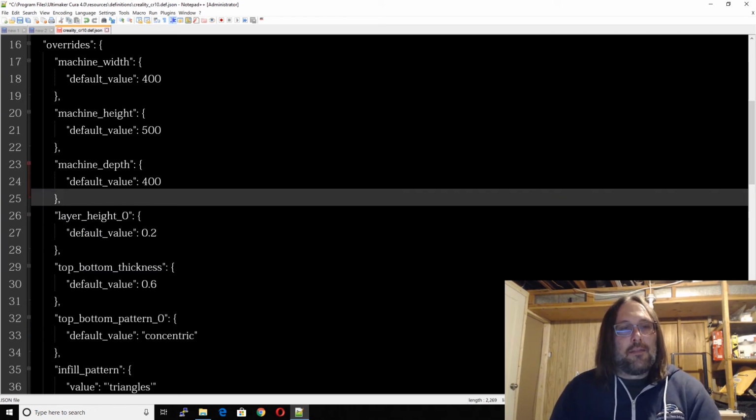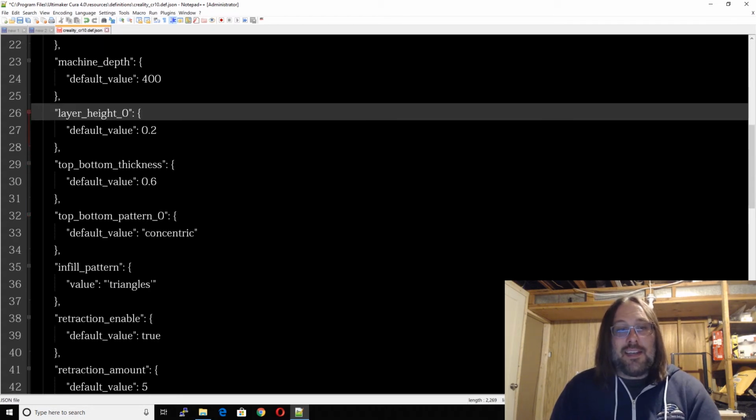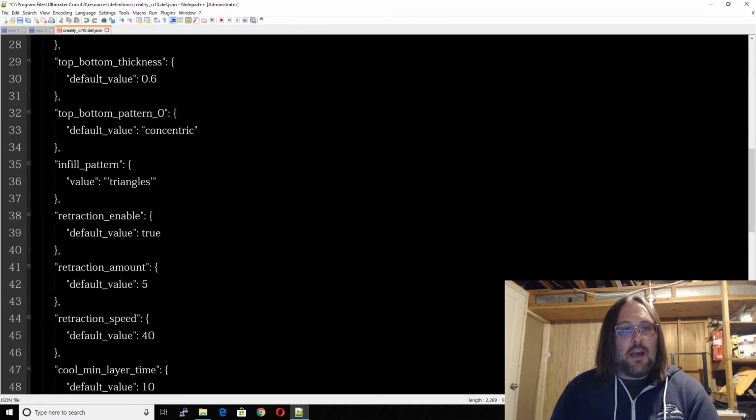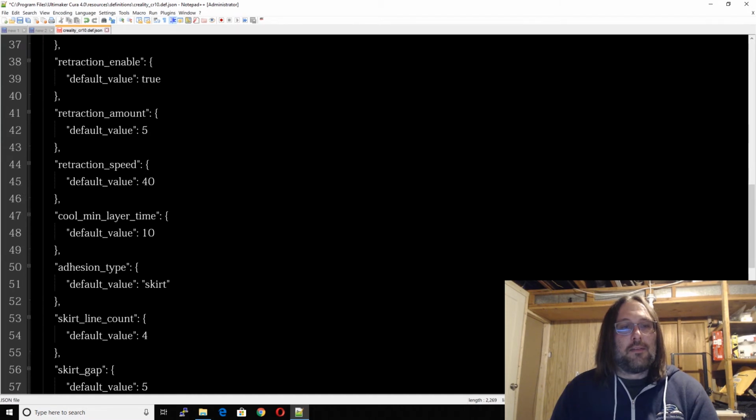You can set some default settings in here. So initial layer height, most of this can stay at defaults now. If you have a magic number, like the Creality products, the 0.04, you can use and set those in here. But right now, everything is okay. Infill pattern, again, all of this stuff we can change in the slicer after when we save some custom profiles.